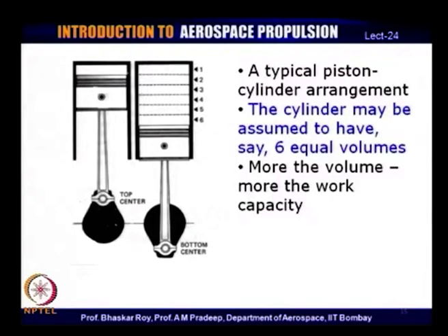And this is what the initial engine mechanical designer will have to decide: what should be the volume of the cylinder which creates the work, and within which the movement of the piston will have to be restricted. So, the volume of the cylinder, or more specifically the volume of the displacement of the piston, is what is to be considered in creating the engine.